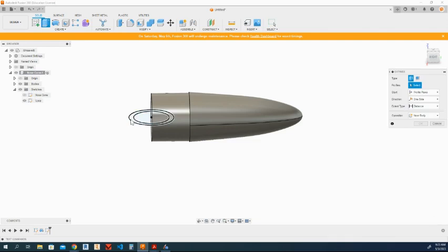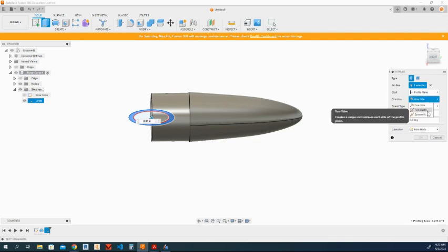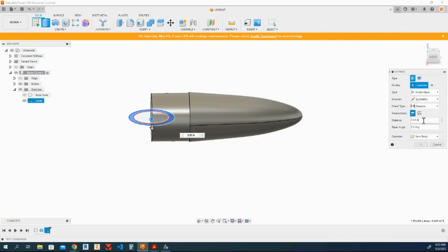Extrude this thing. So I'm going to select that geometry right there. I am going to over here change my direction to symmetric. And I'm going to do 1/2 of 1/8 inch because I'm going two directions at one time. So you can do the math and go, okay, that's actually 0.0625, or you can go 0.125, which is what we used before, divided by 2.